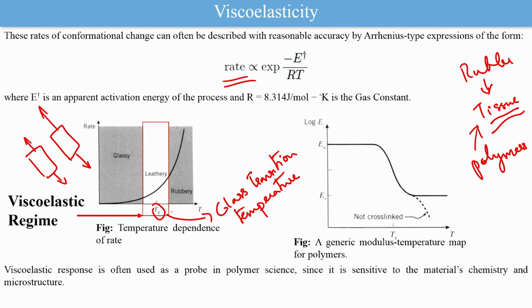And if you heat the material or the polymer beyond it, even this applies to most materials, even glass, what happens is when you heat it above its glass transition temperature, it becomes rubbery or more elastic. Okay. And if the temperature is reduced well below the glass transition temperature, it becomes brittle, and you might already be able to understand why this happens based on the previous thermodynamic explanation that we have already gone through.